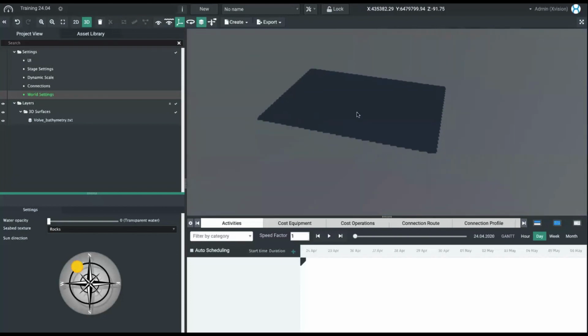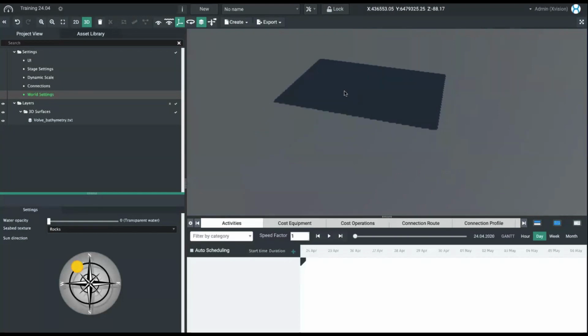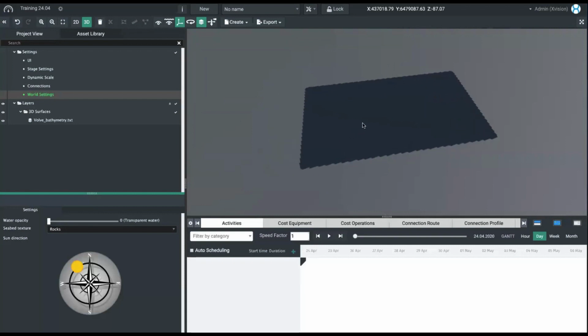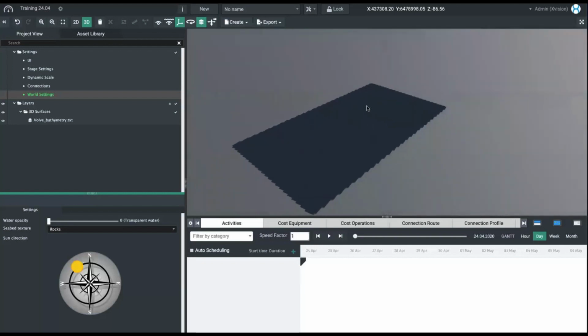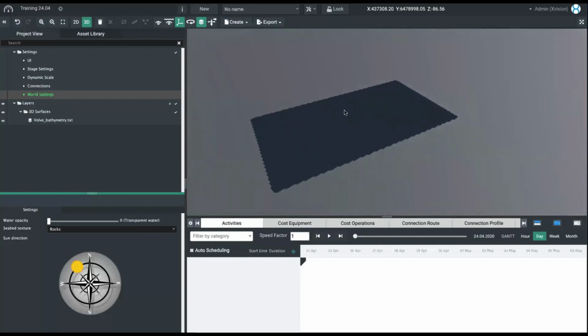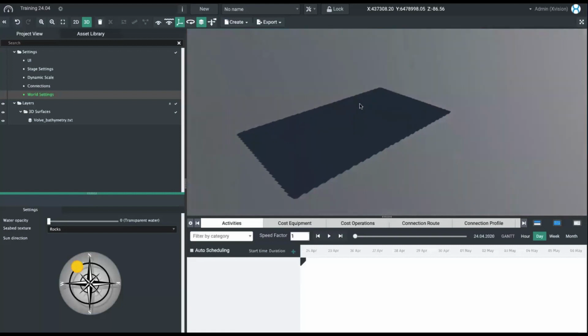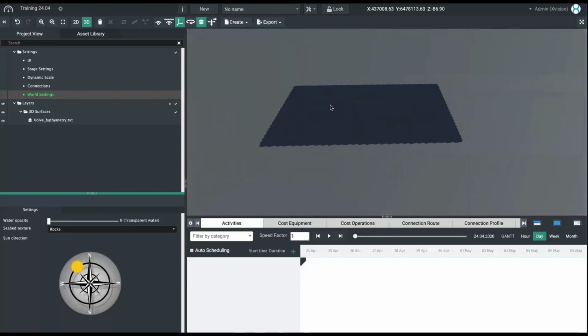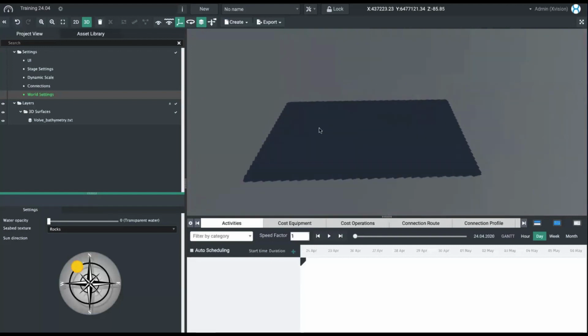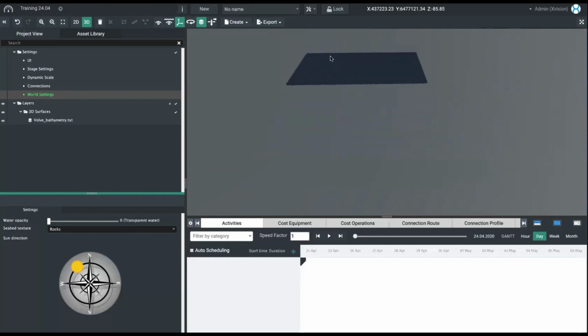While I'm in 3D mode, and this is something that requires a little bit of practice to drive around here, the right mouse button controls the rotation of the scene. By holding the right mouse button down, I'm able to rotate my camera up and down. If I use my left mouse button, I'm clicking a point and dragging that point towards me or from me.